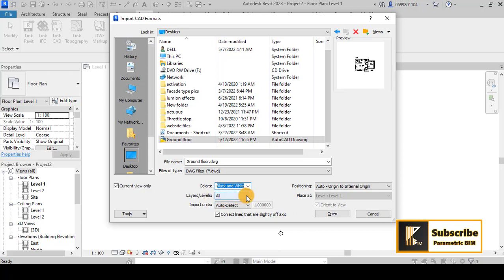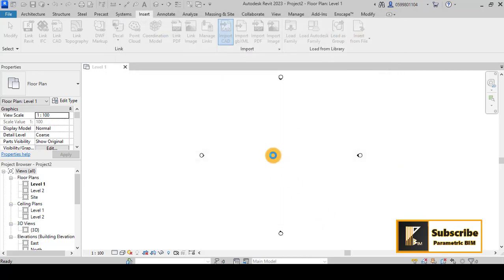And for the import units, I know that I worked in meters, so I will choose meters. For positioning, you have the opportunity to auto link this drawing, but I will choose manual origin or manual center and click open.